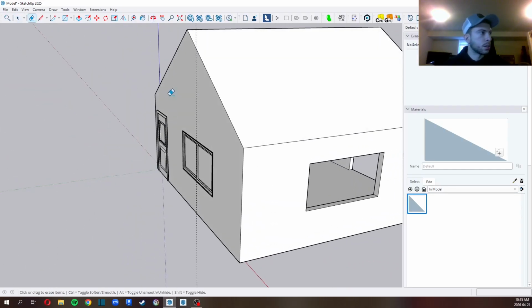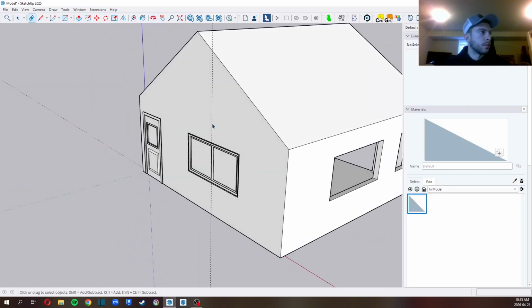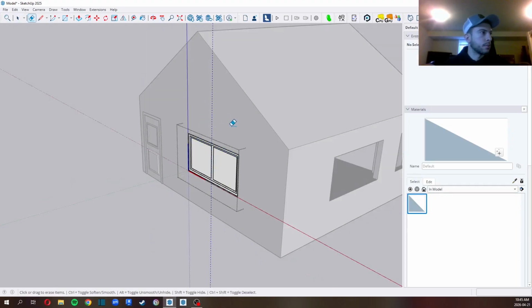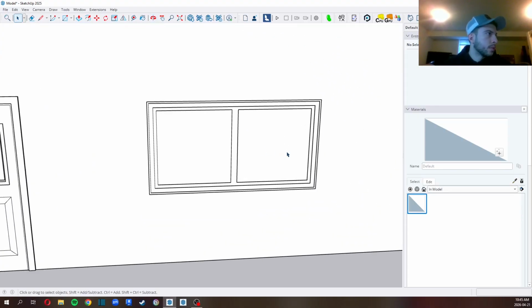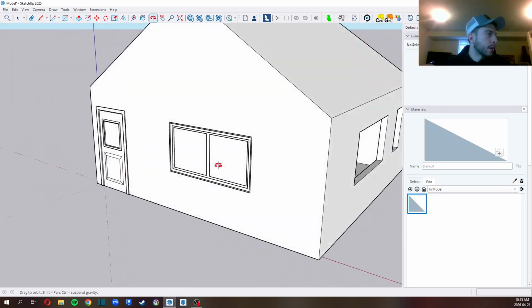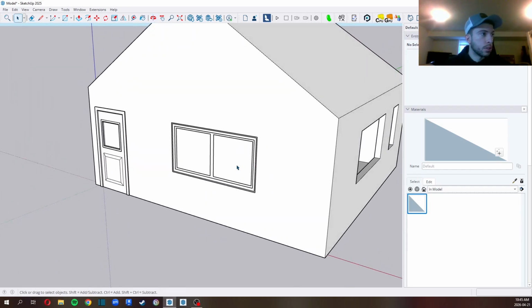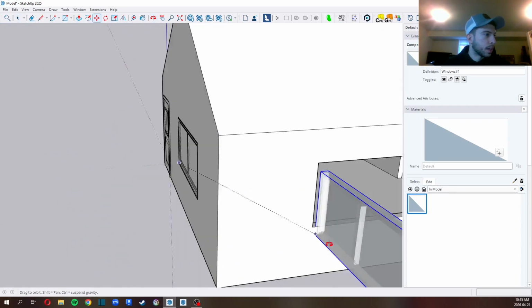Now, it's all depending on if you would like the divider in the middle, or offset to the left, to the right, top, bottom, whatever. But this is where I want to keep it for now. So now what I could do is click that component, M, Control, and move it into my other opening.